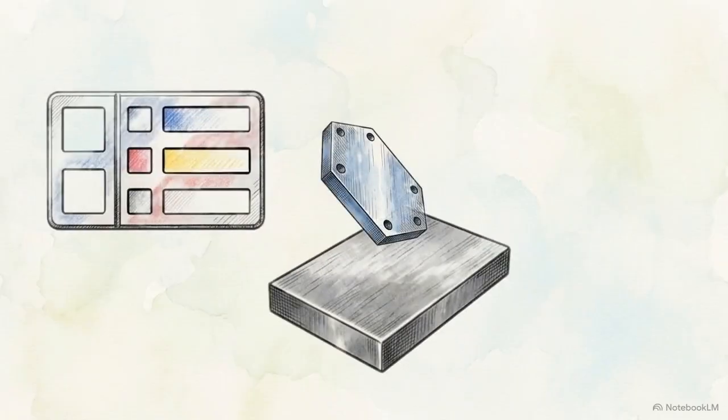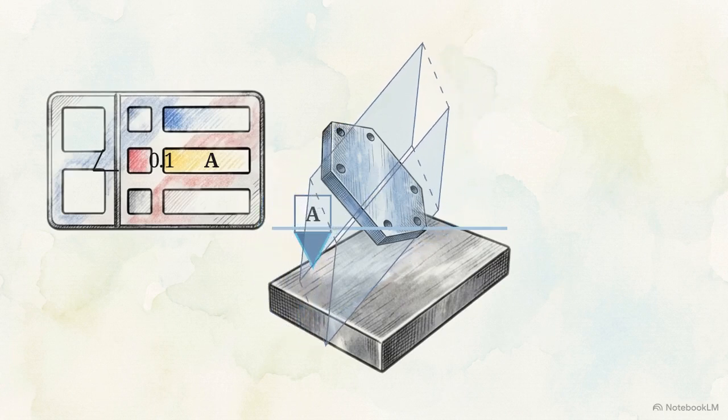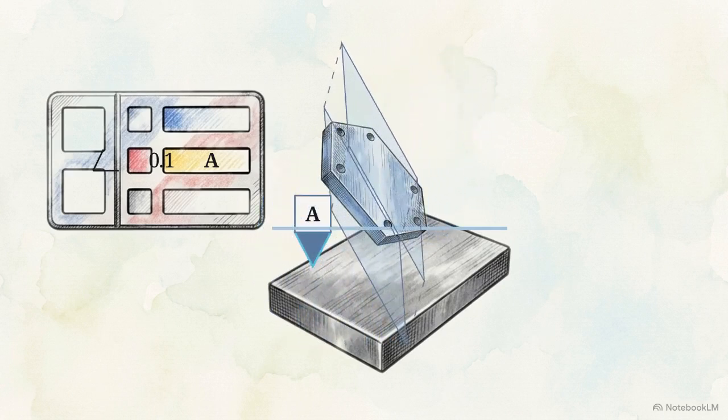This aerospace weldment features an angled mounting plate referencing datum A at the base. You'll quickly see why relying on a single primary datum is rarely enough to secure a component like this. Referencing datum A anchors the specific tilt. However, it leaves the rest of the geometry unconstrained. The entire parallel tolerance zone is free to spin around the vertical axis like a weather vane.